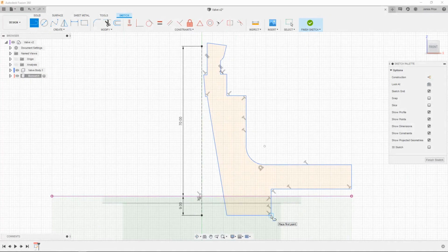Regarding constraints, you will also find automatic constraints placed when creating certain sketch features in a certain way, as with SOLIDWORKS. For instance, in this simple sketch here, you can see a perpendicular, parallel, and tangential constraint automatically applied, as indicated by the glyphs. If this constraint is not wanted, you can simply delete the glyph to remove.